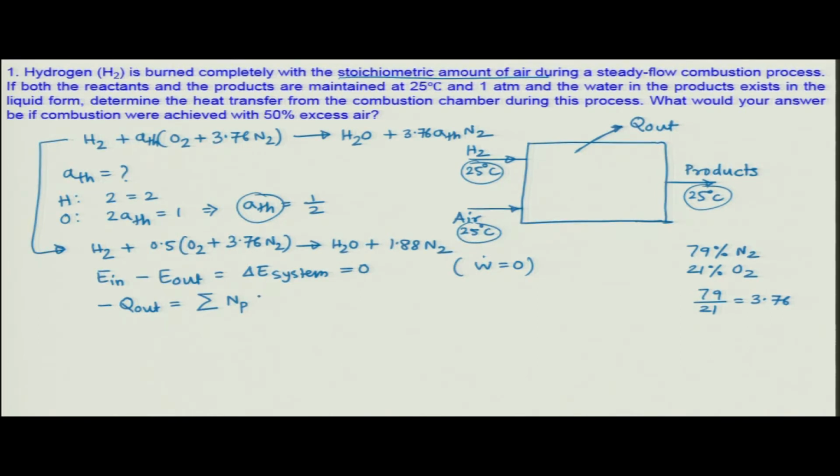that should be equal to the sum of all the species mole fractions times enthalpy. P stands for the product, and here it is the enthalpy. So, I am writing first the enthalpy of formation of each species, and then I will write the sensible enthalpy part, which is basically the enthalpy. This enthalpy H can be obtained at a particular temperature, whereas H naught is basically the enthalpy at 298 Kelvin. And you all know that the bar above enthalpy says that this is the molar unit. Bar represents molar unit.